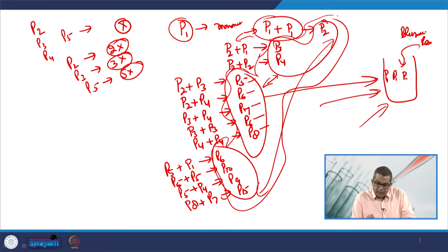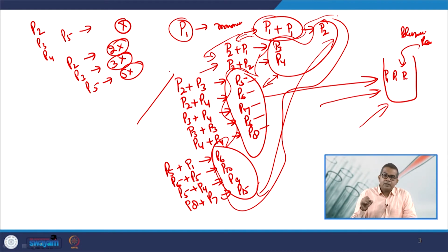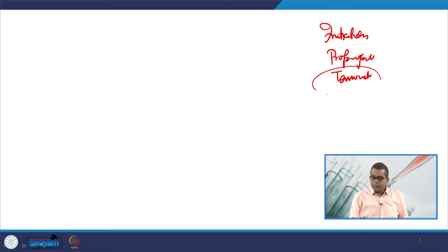Now, the subsequent processes, when you started this initiation process, are termed as propagation. Now, when you achieve the desired property based on your requirement with respect to the thermal, chemical, mechanical or the processability aspect or viscosity aspect, then you try to truncate. You cannot carry out this particular polymerization process for an infinite period, because I told you that it may create a bulky mass. So, in that case you prefer the termination.